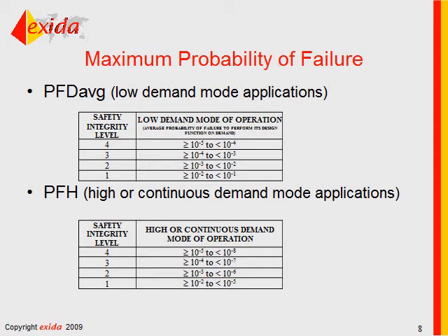As a quick example, if you look at an operator in an automobile manufacturing plant who is pushing sheets of metal in a big press, that safety instrument function basically needs to work continuous. Even if it detects a failure, then arguably the operator that pushes a sheet of metal in the press every minute or so doesn't have time to react on any detected failure.